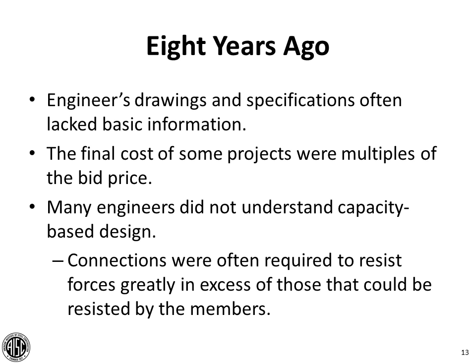But the engineers may not have totally understood the capacity design, capacity related design concepts, and so therefore they weren't designing those other members to resist those forces. So you had connections that were held to a much higher loading standard than the rest of the structure in some cases, and you end up with a lot of reinforcing, and it was difficult to figure out when that reinforcing should end or whether that reinforcing was necessary. And that was really the big problems that were occurring about 8 years ago.